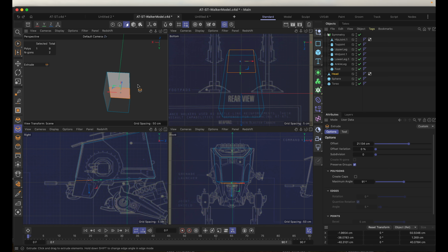Whereas if I just click on the polygon itself, oh wait, they fixed it. Maybe they fixed it in this version. That's fantastic. So it used to, if you selected it, oh, there we go. If you select right in the center, it's going to stretch the whole thing, and that's not what you want to have happen. You want to click and drag. And I want you to note every time you click, you may not see anything change, but every time you click, it's going to create a new subdivision. That can be your enemy or your friend.